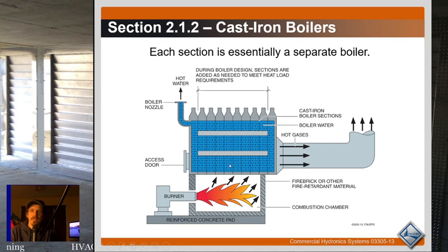It's pretty easy because you've got to transfer that heat to the air, so it needs to be kind of thin, right? With furnaces, you're basically guaranteed to crack that heat exchanger down the line at a seam or something like that. With these boilers, it's a lot less likely that you're going to end up with a cracked section, as long as everything is operating well.